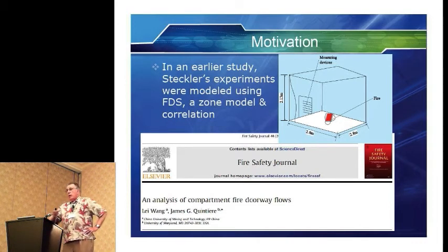The thermocouples were not ordinary thermocouples. They were aspirated thermocouples to correct for any radiation error. Because in any fire experiment, you have a radiation error. And if you just look at the thermocouple data and compare with some model, you better correct the data first if you're looking at temperature. So these were aspirated probes to give us a good measurement of what the temperature was. And the bidirectional probes were also calibrated, because they depend on the Reynolds number or the flow rate. If you get too low in flow, that factor in there that's like a Bernoulli factor changes with the Reynolds number.